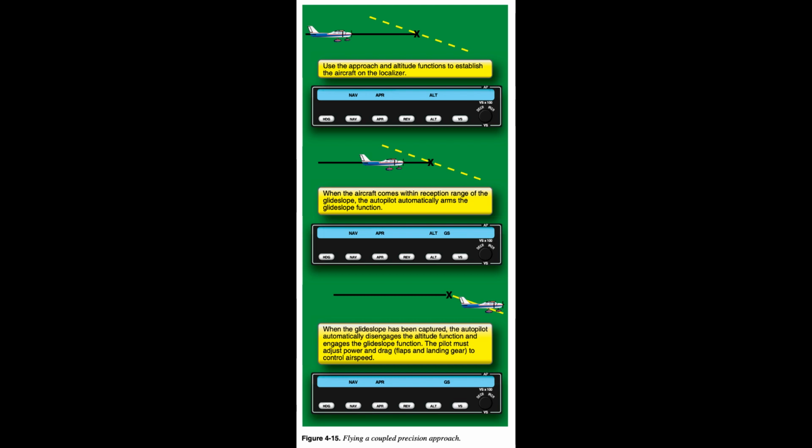The FD/autopilot attempts to perform as programmed by you, the pilot. If the climbing vertical speed selection is too great, the aircraft increases the pitch attitude until it achieves that vertical speed, or the wing stalls. Selection of an airspeed or descent rate that is too great for the power selected can result in speeds beyond the airframe limitations. Leveling off from a descent, without restoring a cruise power setting, results in a stall as the FD/autopilot attempts to hold the altitude selected.